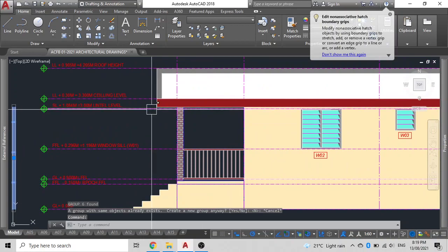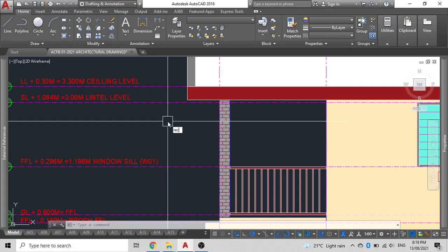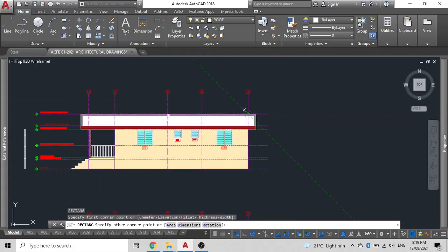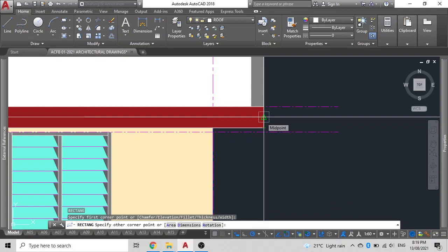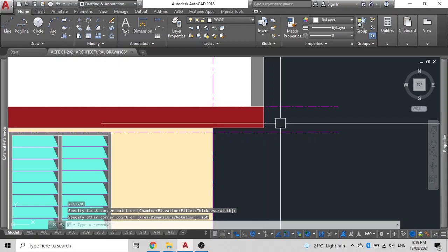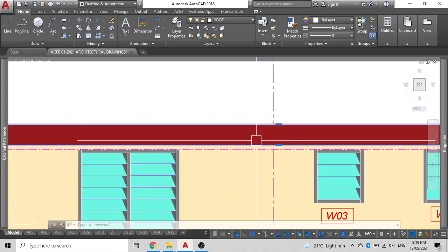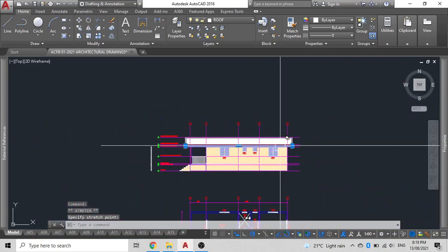Now over here, what I'll need to do is simply do a rectangle REC from this diagonal to over here, and then I'll just move it up. So I enter my distance as 13,400 and press tab, or you don't have to actually, it's already entered the distance. You can just enter a distance of 150 and press enter. And that is the outline of my gutter.